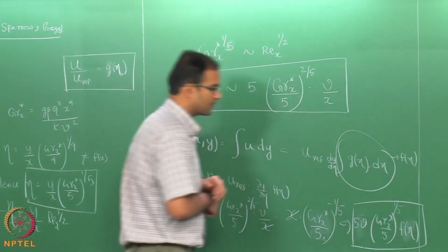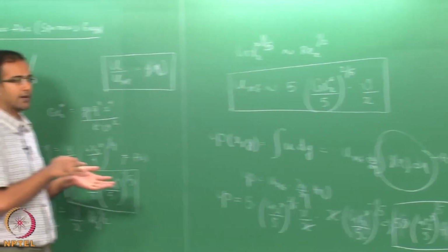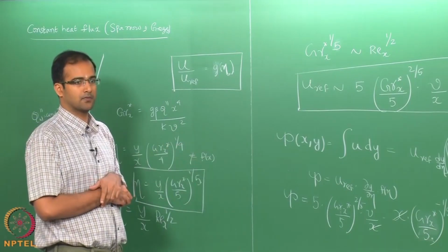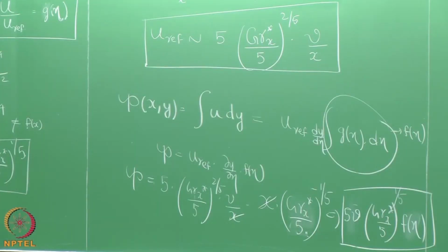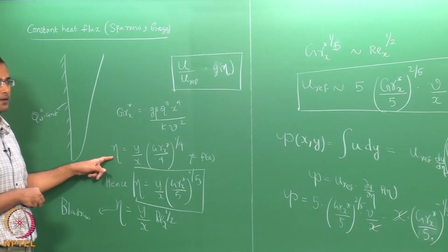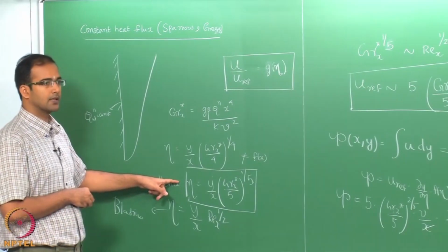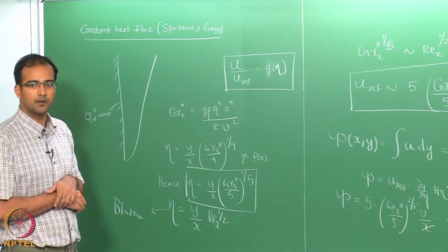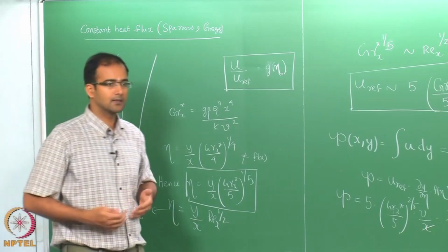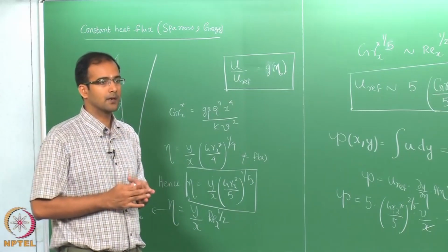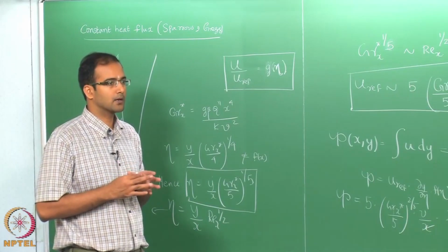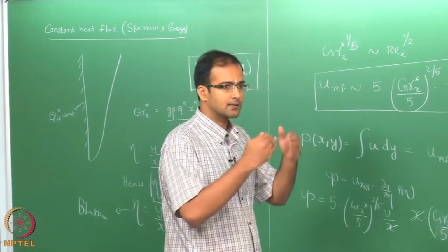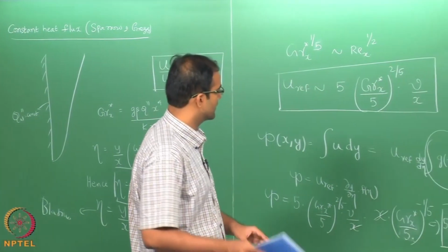So we know the transformation from the flow field in xy coordinate to eta through the relation between psi and f. Okay. Also we know the basic transformation through the similarity variable. So, therefore, now we can substitute this into the governing equations, the momentum as well as the energy equation, the same way. Substitute for u, v, du by dx, du by dy, d square u by dy square, and you will be able to reduce these partial differential equations into similarity equations.